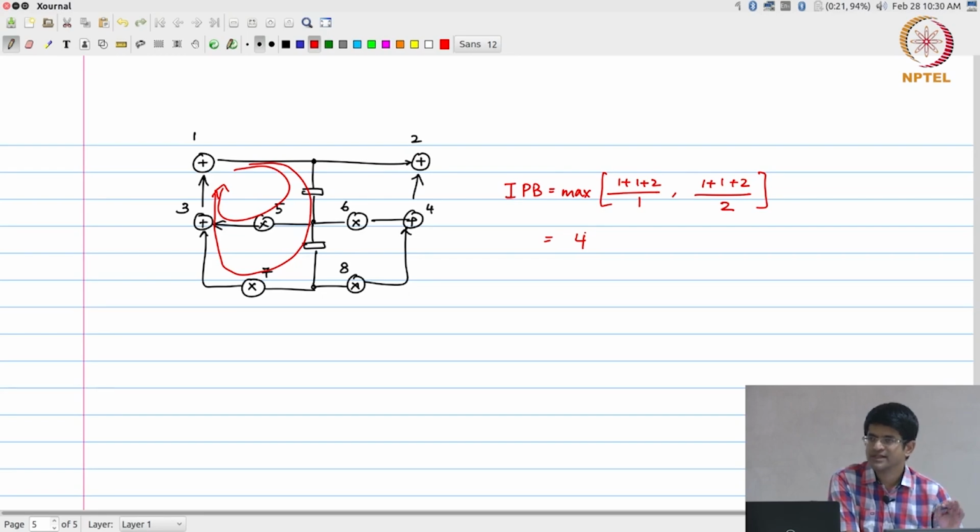So 4 is a reasonable value to target, and it just so happens that if I can get n equal to 4 and then achieve the rest of the implementation using 1 adder and 1 multiplier, that's great, because I would actually hit 100% hardware utilization. It's a coincidence in this case, because n equal to 4 and the fact that there are 4 multiplications and 4 additions is just incidental. There was no requirement that it should automatically be the case.